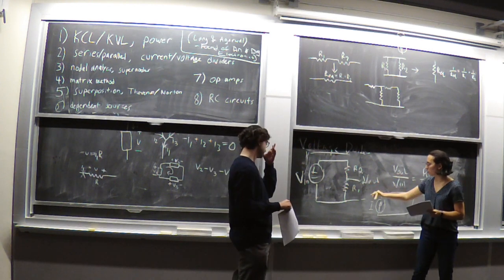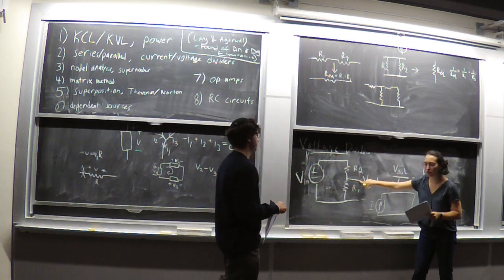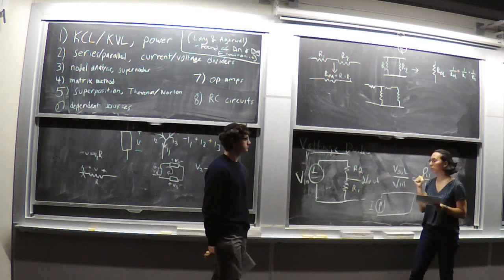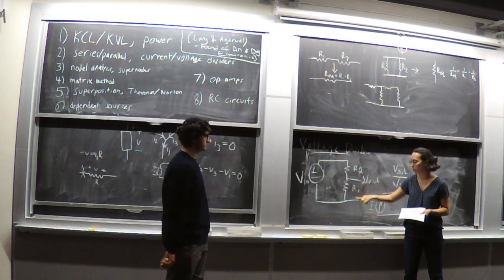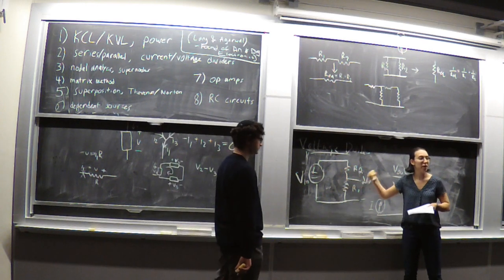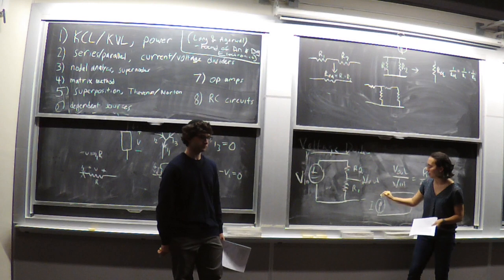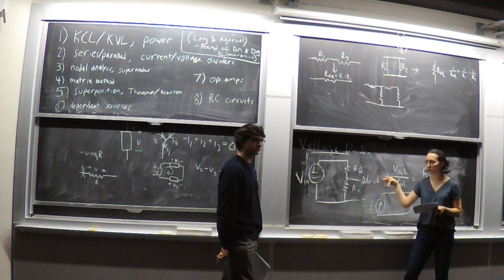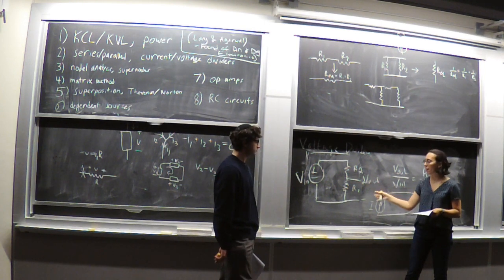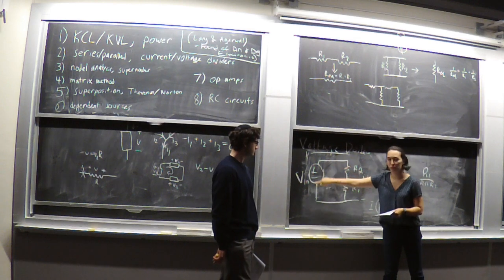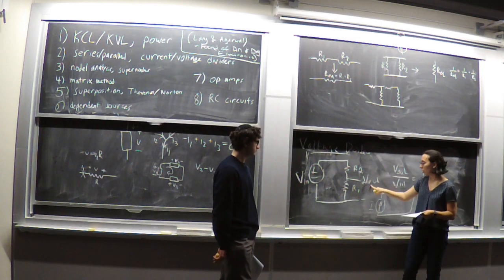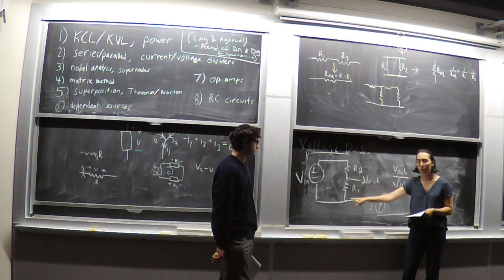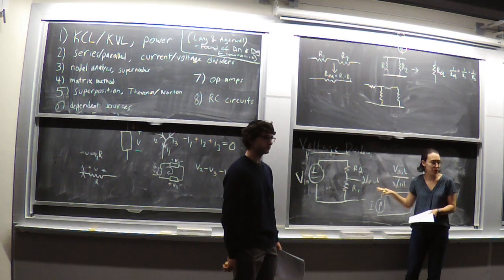There's a big difference between when we draw something like this. So I've drawn just a wire with a plus sign, a wire with a minus sign. This means you're taking your probe and you're measuring the voltage you get out here. Like you put your ground probe here and you took your other probe, you put it here, and you measure that voltage. That's very different than saying that there's a voltage supply between those two terminals. Does that make sense? If there's a voltage supply through two terminals, then current can flow through it. Like there is current flowing through this V-in source. But there is not current flowing from the minus terminal to the plus terminal in this direction. There would be current along this branch, but there is no current here. This is simply a passive measurement you're making.